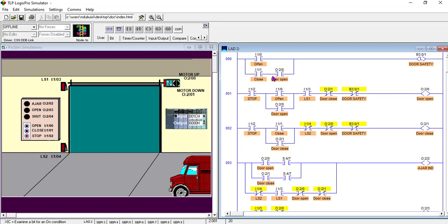Now if this door open motion is on, once you press close, this will activate. So now I need the door close to complete the program. Oh, I haven't put the contact. I put the contact, so now I have to put the door close. So now if the door is closing and you press open, you activate this. You see, that is it. But we need to reset.